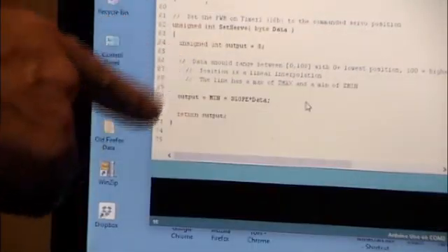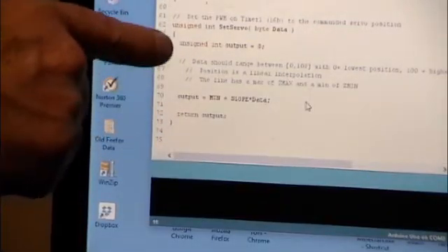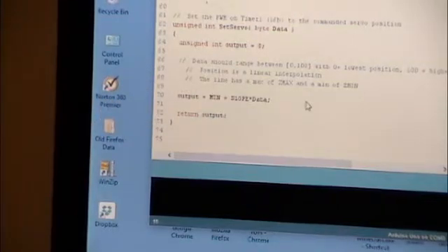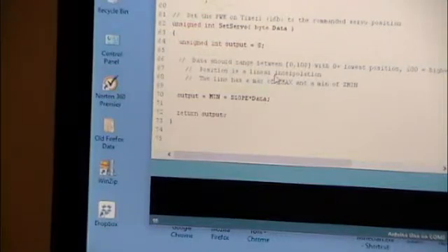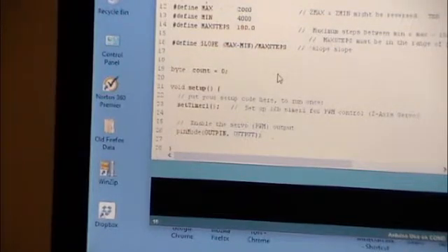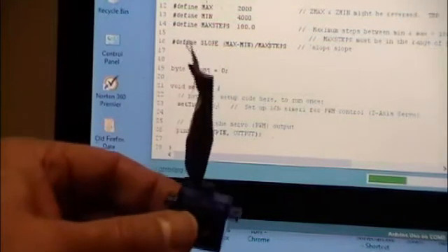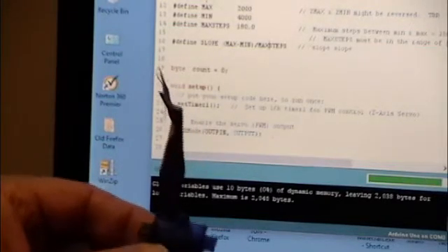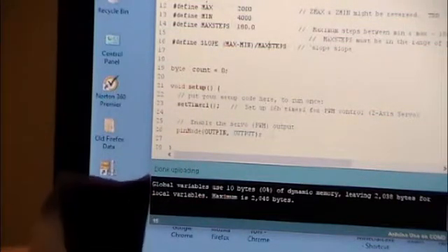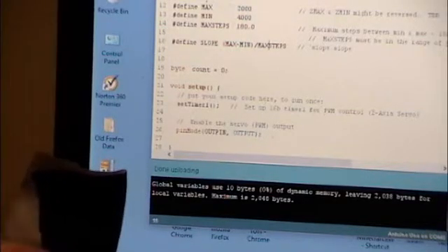And then there's another couple of lines of code where I do some math to say, when I'm at this many degrees, that means my pulse width needs to be this. So it's basically a slope offset math calculation. So that tells you that the whole servo library is about 15 or 20 lines of code for a servo object. But if I load him up, so there he goes, doing pretty much the exact same thing as before, only it took me 30 lines of code because I didn't use their library.